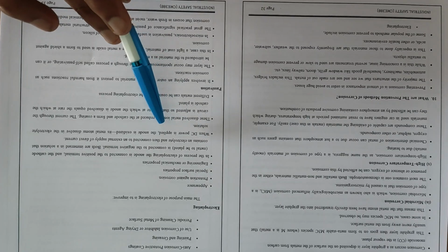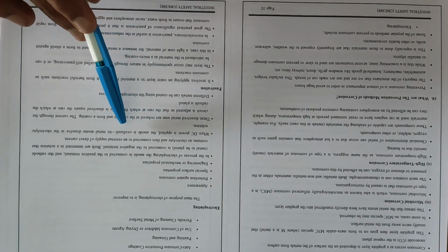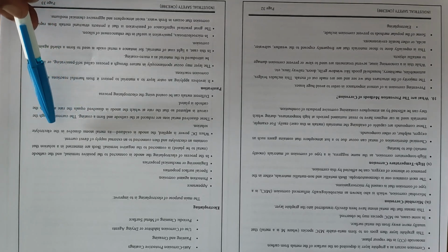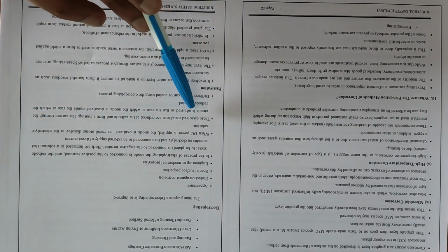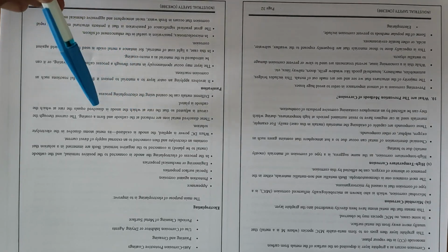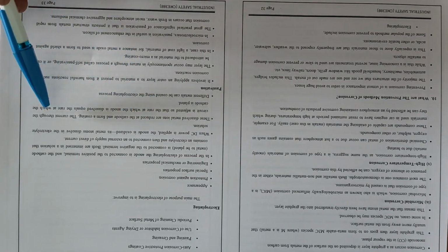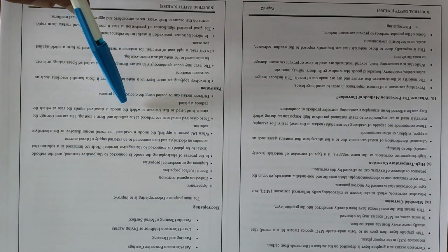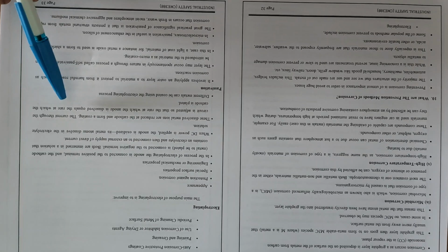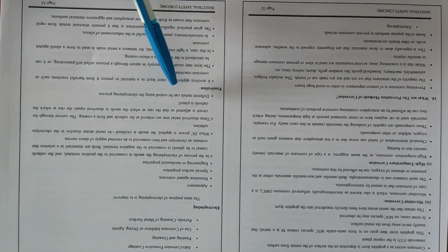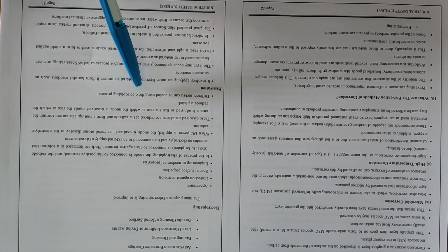When DC power is applied, the anode is oxidized. Its metal atoms dissolve in the electrolyte solution. These dissolved metal ions are reduced at the cathode and form a coating. The current through the circuit is adjusted so that the rate at which the anode is dissolved equals the rate at which the cathode is plated. Different metals can be coated using the electroplating process.